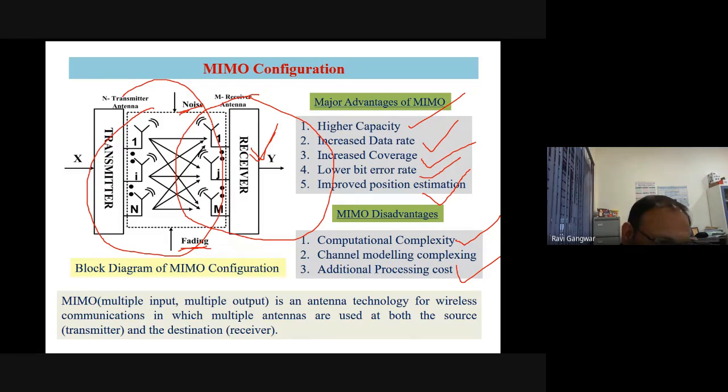So at antenna 1, antenna 1 receives 4 different signals from the 4 transmitting antennas at a time. Similarly antennas 2, 3, 4. So at the receiver side you have 4 antennas and each antenna receives 4 signals, minimum 4 signals. Then this receiver needs a system that can process 16 signals at a time. Clear? That is your minimum requirement. It means you have to design a system in such a manner that it can handle 16 signals or more than 16 signals.